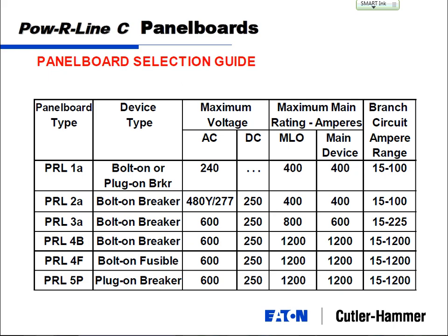The solid state is a little different in that you can see cables actually connect through the breaker and can come out here, for example, and inside of this trip unit are CTs, current transformers. So in a solid state trip unit, you are sensing the current that is flowing through the trip unit and digitally modeling it inside this trip unit.